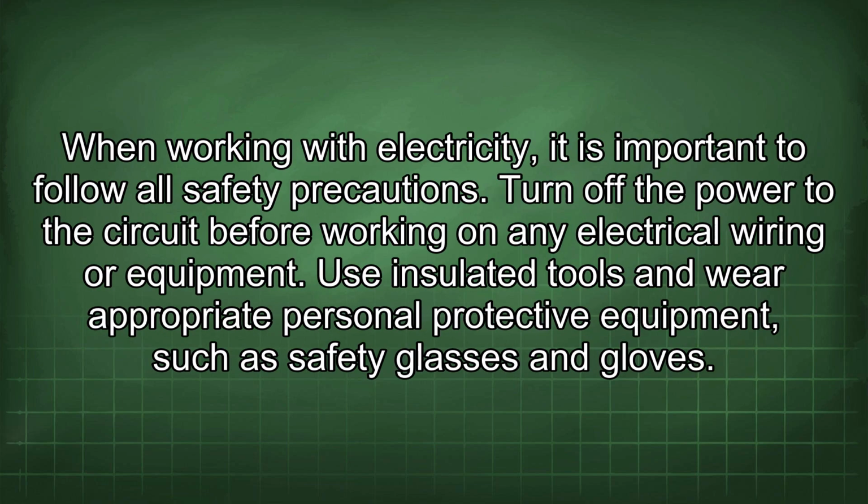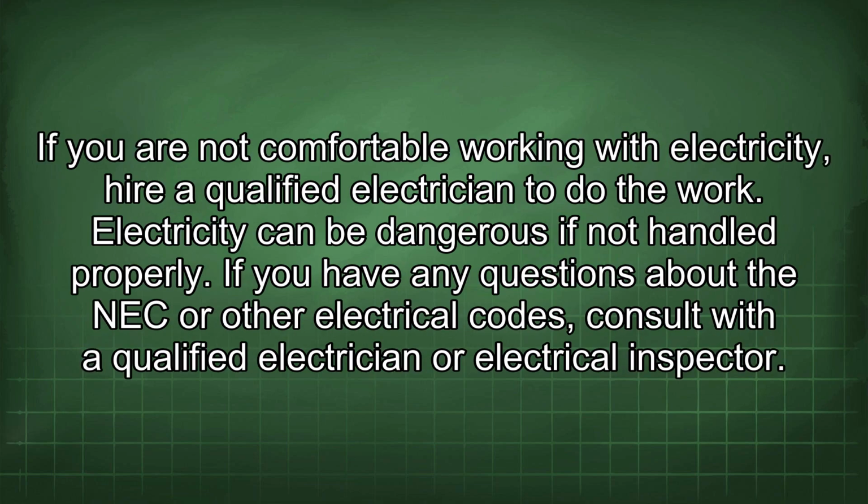When working with electricity, it is important to follow all safety precautions. Turn off the power to the circuit before working on any electrical wiring or equipment. Use insulated tools and wear appropriate personal protective equipment, such as safety glasses and gloves. If you are not comfortable working with electricity, hire a qualified electrician to do the work. Electricity can be dangerous if not handled properly.